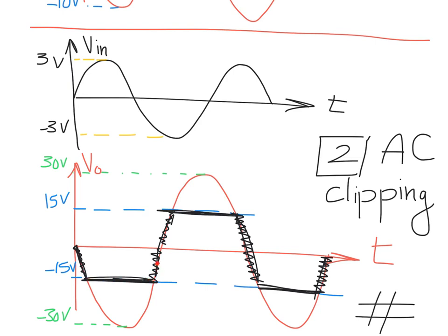Again, if you have output voltage minus 14, minus 3, 3, 12, 15, it's okay, you will get the same values. If you get output voltage 18, 20, 25, 29, 30, all these values at the output will be just 15 volt. And this is called a clipping circuit.